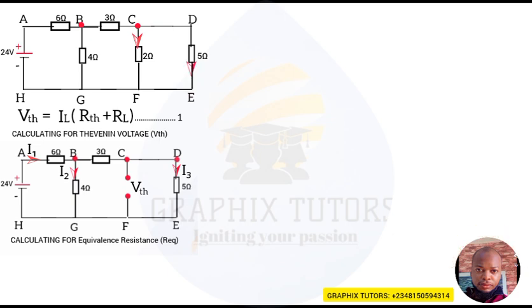So instead of my R equivalent, I will use R sub A, because the same current flowing through the 3 ohm is the same flowing through the 5 ohm. We say 3 ohm and 5 ohm are in series. So R sub A is equal to 3 plus 5, which is 8 ohm. So I'm going to change this into one single resistor, and that is 8 ohm.